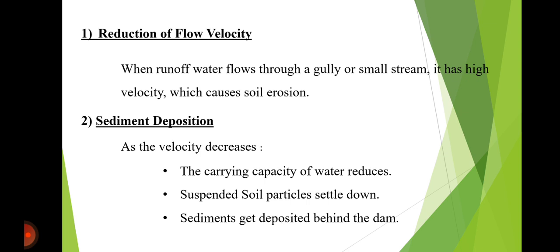Sediment deposition. When the velocity of water decreases, its ability to carry soil particles also decreases. Sand, silt, and other sediments settle behind the check dams. As the velocity decreases, the carrying capacity of water reduces. Suspended soil particles settle down, and sediments get deposited behind the dam.